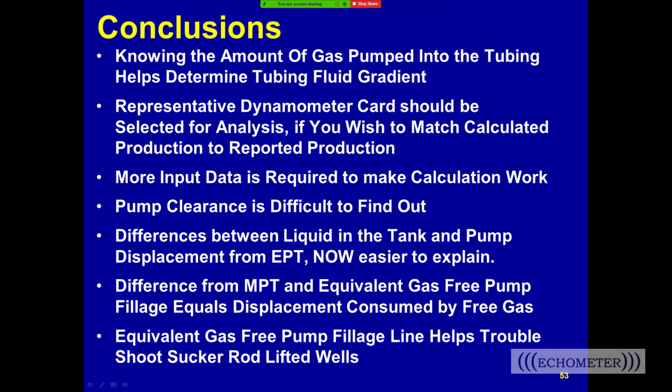Right. Well, the heavy oil doesn't behave the same. So I've got data from a lot of wells in Venezuela, probably over 100. And those wells were around 8,000 foot deep. The viscous fluid causes more dampening on the rod. We talked about this on the second Ask Echometer: when the pump card is concave outward, like a bowl, then you can increase your damping factor and flatten the pump card out. And that's fluid friction.